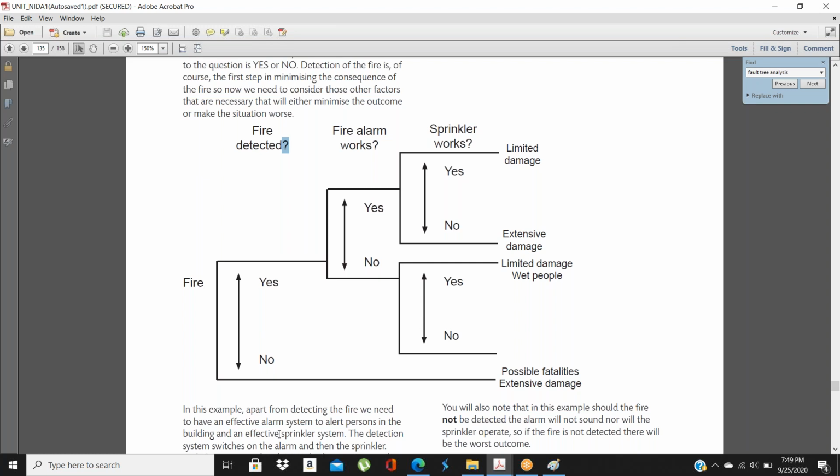Basically, now that the fire is occurring, in the event analysis we are seeking the recovery and the damages, the consequences. And we are estimating the consequences exactly. If we use both of these, we can use a bow tie analysis that combines both analyses.